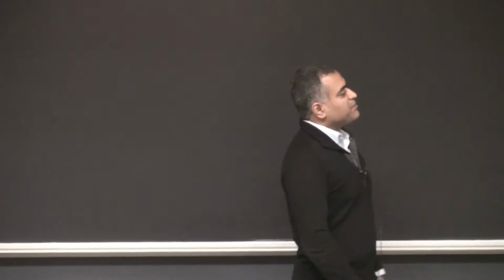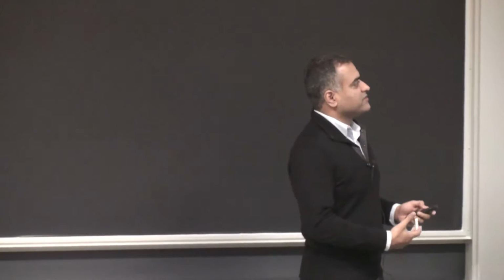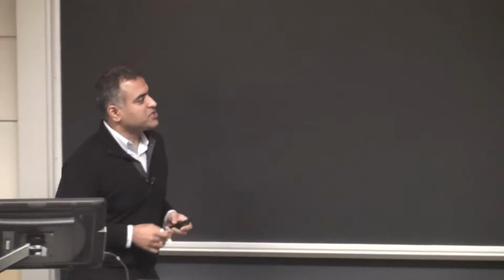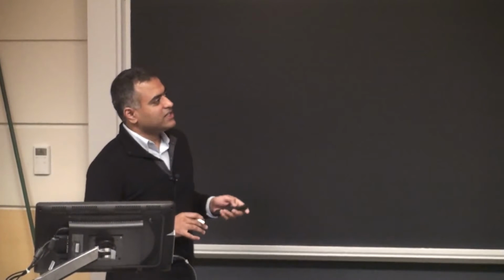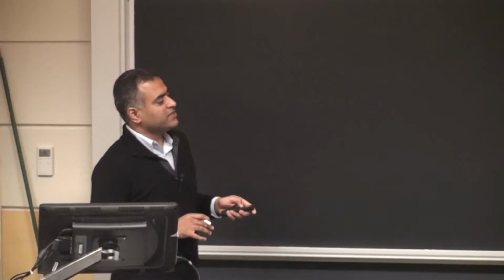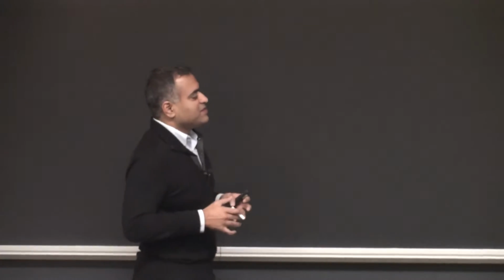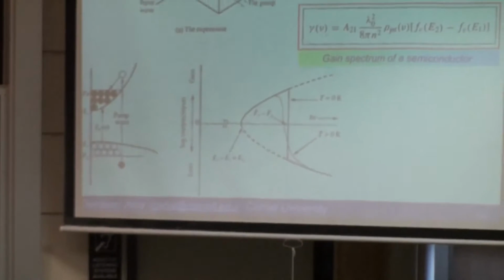So we are going to look at both of them, and then apply the same techniques as earlier of writing down the rate equation, getting spontaneous emission, stimulated emission, and absorption. Once we understand this whole picture, you can turn the semiconductor system around and either make a laser with it, or an LED, or a photodetector, or a solar cell.